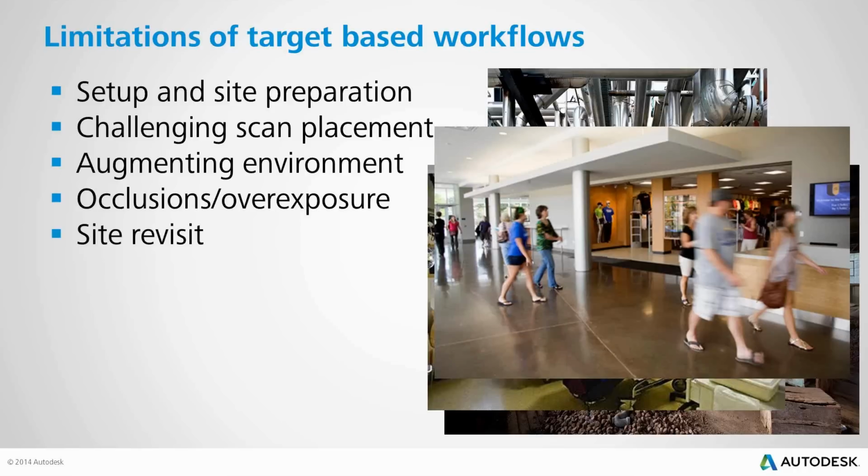Site revisit is definitely an issue. Let's say you've collected 100 scans and you get back to your office and then you realize that a couple of your scans were bad, or you missed an area of your environment. Now you need to go back out, but you've already taken down your targets, and there's not a nice, easy way to tie these additional scans back into what you've already done.